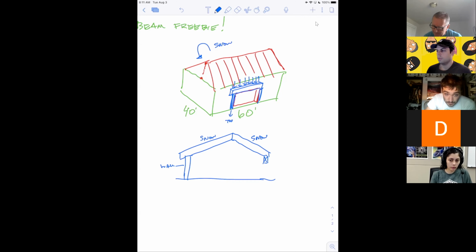You don't need to know this, but roofs, at least where you live in Medford, are 40 pounds per square foot is how much the roofing, that's accounting for the roofing. Because remember, there's weight on the roof even if there's no snow, but the snow, which is called live load, kind of comes and goes a little bit.